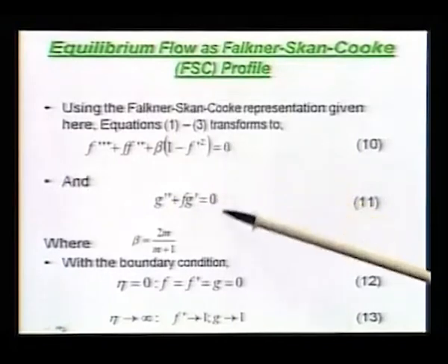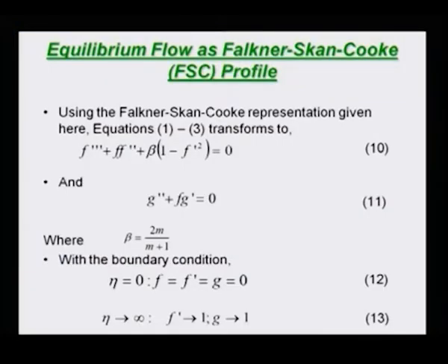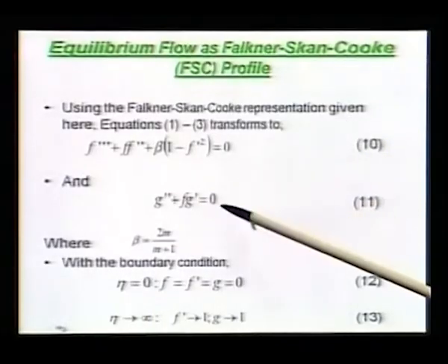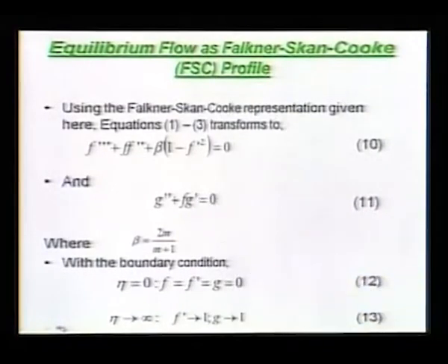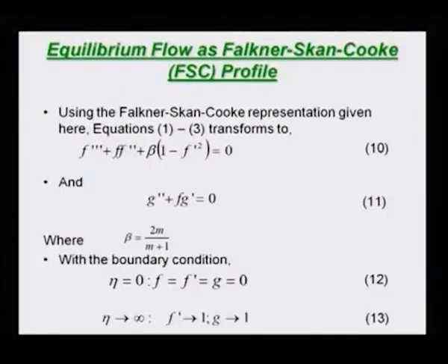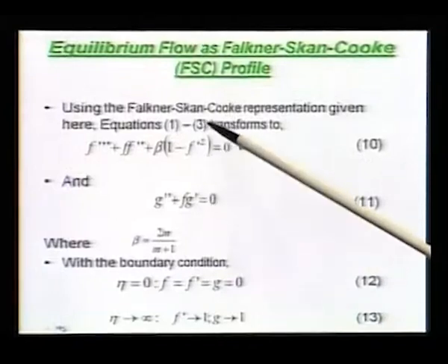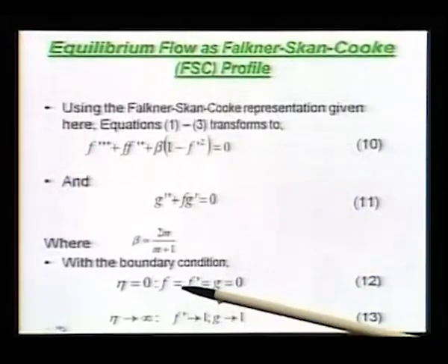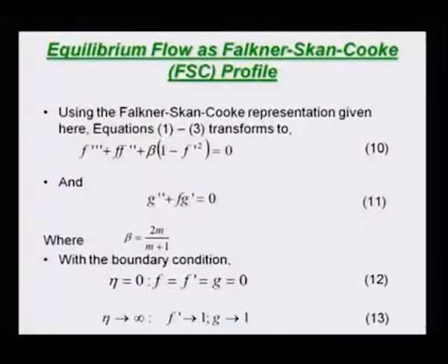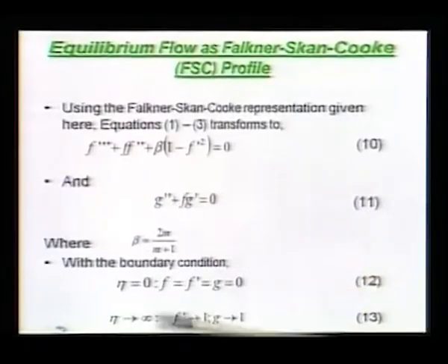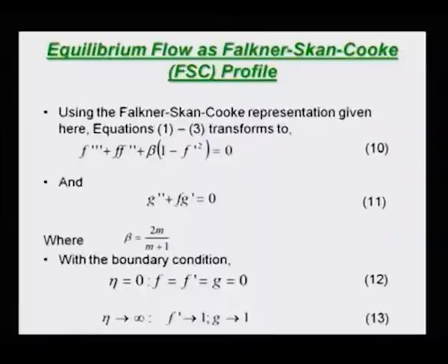So what you notice, of course, directly from here, is that f can be solved independent of g. So first you will be solving for f by solving equation 10. Once you have the f, you can plug it into equation 11 to get the g. So this should possibly help you in defining the flow field. So you need to solve these two equations. These are ODEs. So it's a third order ODE, so you require 3 conditions for f, and a second order ODE in g will require 2 conditions for g.